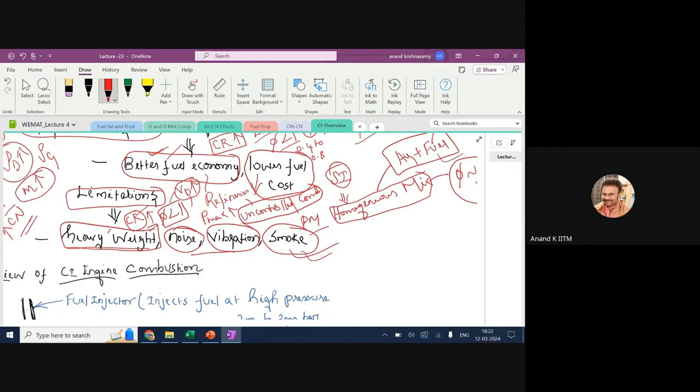So smoke is nothing but a gas stream which carries soot, which are solid particles. It also carries liquid particles. Liquid particles are unbound hydrocarbons. The source for this is fuel, and the source is also lube oil, lubricating oil.